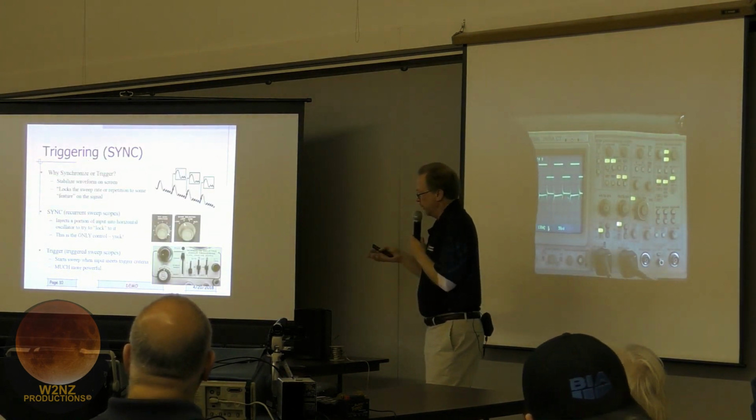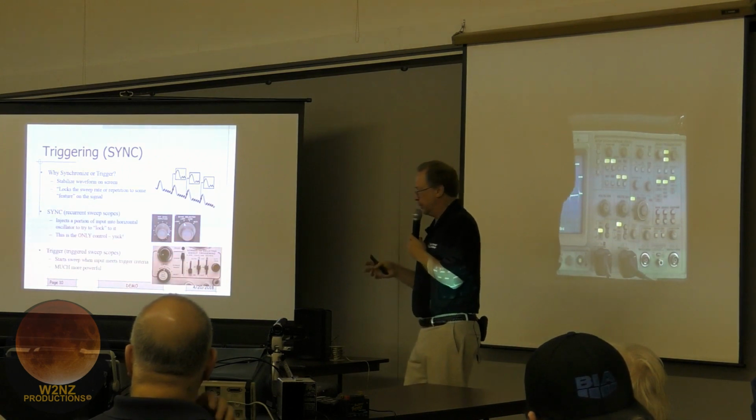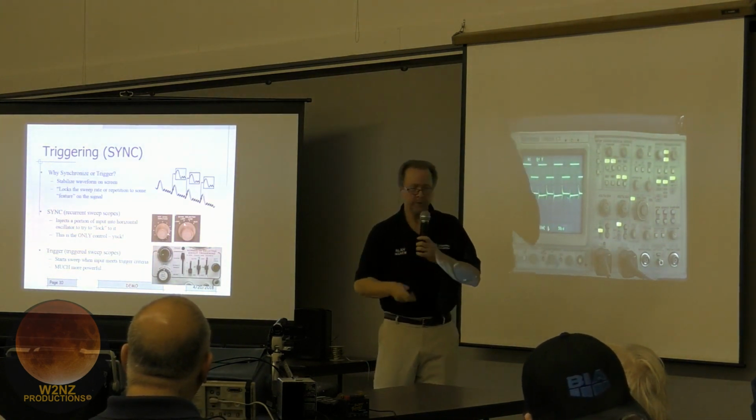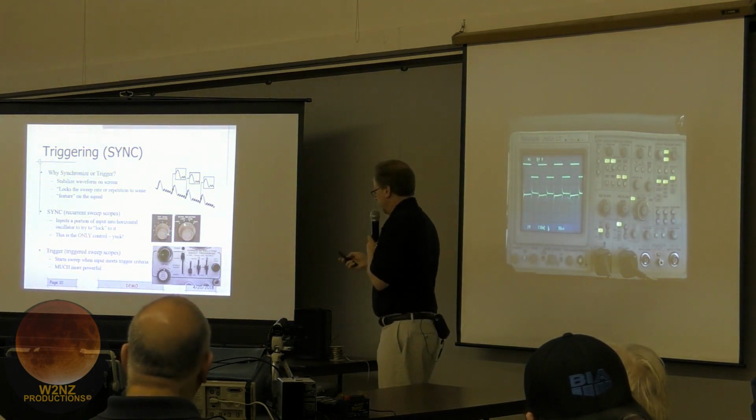So, really when we're going to talk about that, we'll talk about triggering. Triggering is saying, when am I going to sweep that signal across? Okay, when am I going to start that sweep? And ideally, you want to start that at the same location in time on a particular waveform.